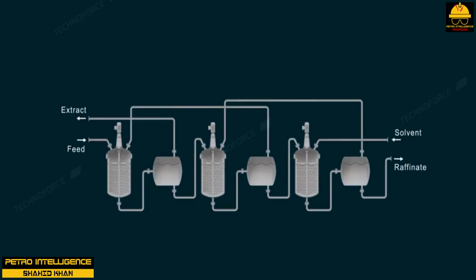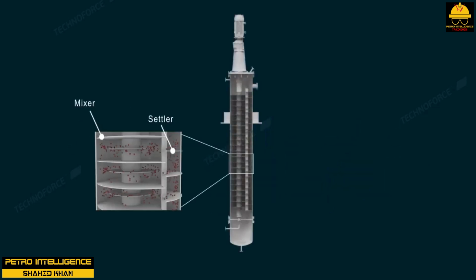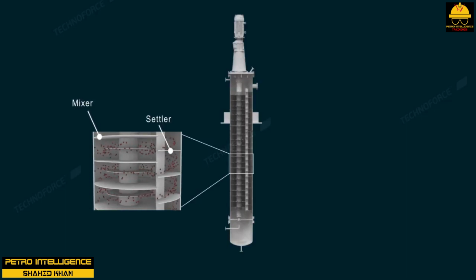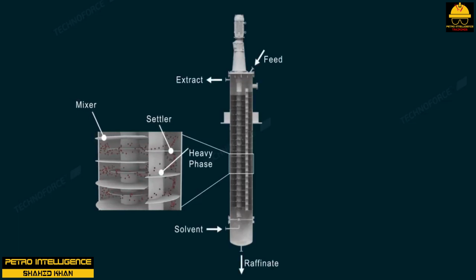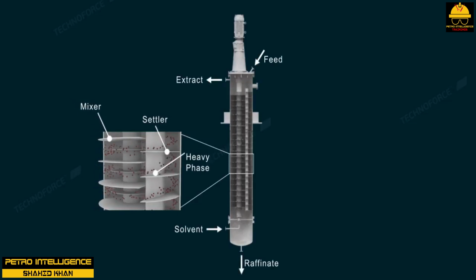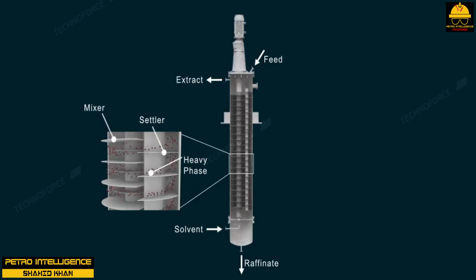Such a process could be converted to continuous operations by continuously adding the feed and solvent and continuously withdrawing the raffinate and extract. For such a process to be successful, some means of mixing or contacting the materials must be provided while still allowing ample space for the raffinate and extract to layer out. Many simple yet ingenious means have been employed for this purpose. Most frequently, a single-stage device as described will not provide a perfect separation, and the raffinate must be contacted again with more solvent to complete the removal of all solutes.